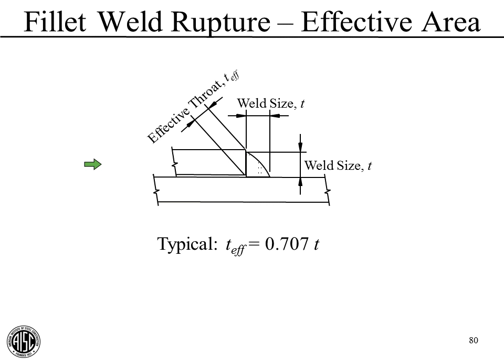The design model is that the weld fails through the critical section, which is going to be the minimum section through here. The minimum section through the weld like that on this 45-degree angle in this case. Now the width of that critical section we call the effective throat, and we'll call it T sub EFF in our work here.